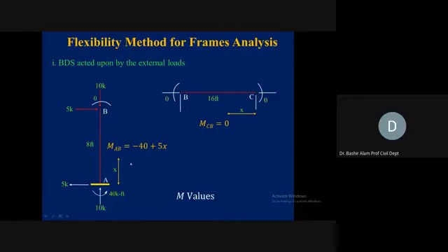Now, this equation is clear, MAB, we are writing this with respect to the origin A. For BC, we are taking the origin C. All the member end actions are 0, so it means the moment equation will be equal to 0. You can check the limits also and the I's also, because we will be needing these values again in completing the table.